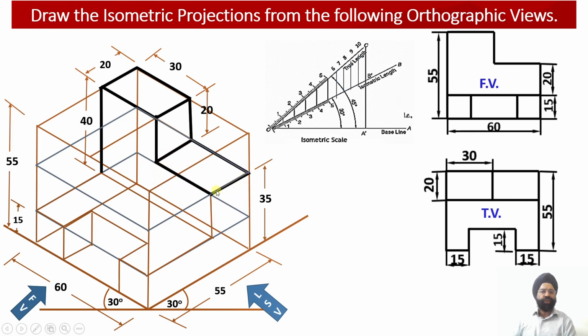So this is my horizontal surface over here, right? So this is my horizontal surface which appears in the top view like this face, and in the front view this horizontal surface will be appearing as an edge view in this orthographic projection. And then I will be moving down over here. This height is equal to 20 millimeter, and on this side this height is equal to 35 millimeter. And then let me complete the horizontal part of the web.